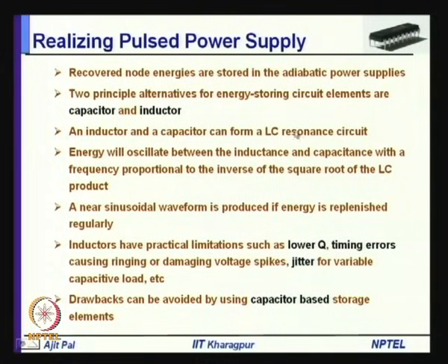the pulse power supply. We are not going into the details of realization of the pulse power supply, that is an area of research, how we can realize the pulse power supply very efficiently. The efficiency has to be very high, otherwise if the pulse supply is not efficient, whatever gain you achieve in the adiabatic circuit will be lost in the power dissipation of the power supply.